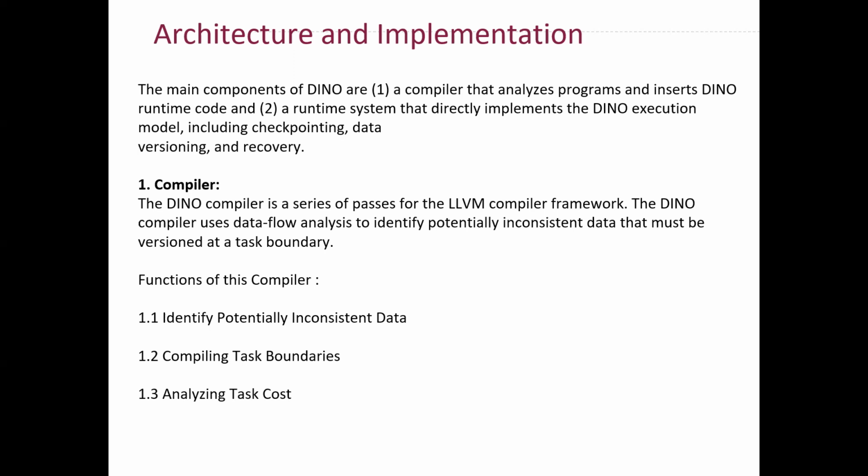Now the programmer inserts task boundaries, which are also called the DINO task. Encountering such a call, the DINO compiler first determines the set of non-volatile variables to version using the analysis we discussed in data versioning. Then it replaces the call to DINO task with calls into DINO's runtime library that version the relevant non-volatile state, which is the DINO version, and checkpoint volatile state, which is DINO checkpoint. So the program is linked to DINO's runtime library that implements these functions.